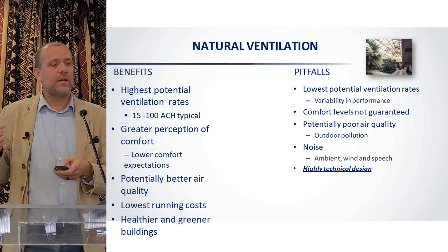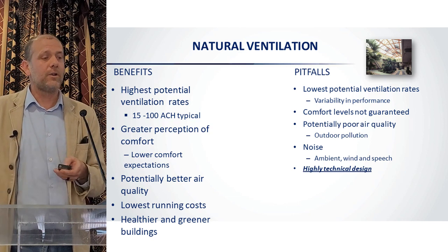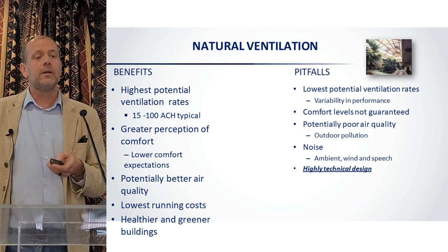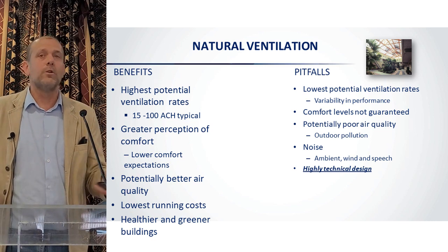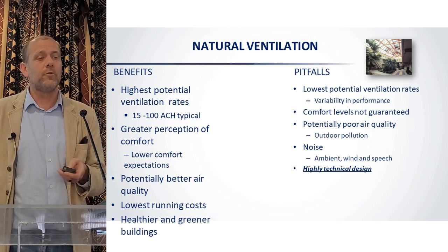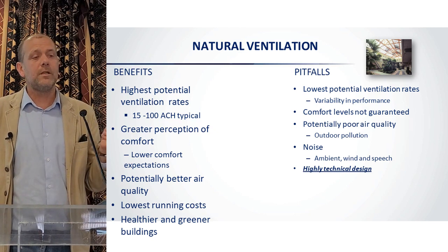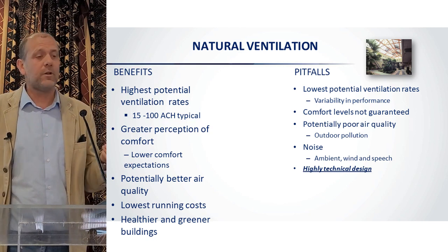You've got potentially better air quality. You've got lowest running costs. In some cases, no running costs. You've got healthier and greener buildings. However, when the system fails, when the windows are closed, if the wind's not blowing at all, you've got potentially the lowest ventilation rates because of the variability in performance. Your comfort levels are not guaranteed. You've got also potentially poor air quality if no air moving.